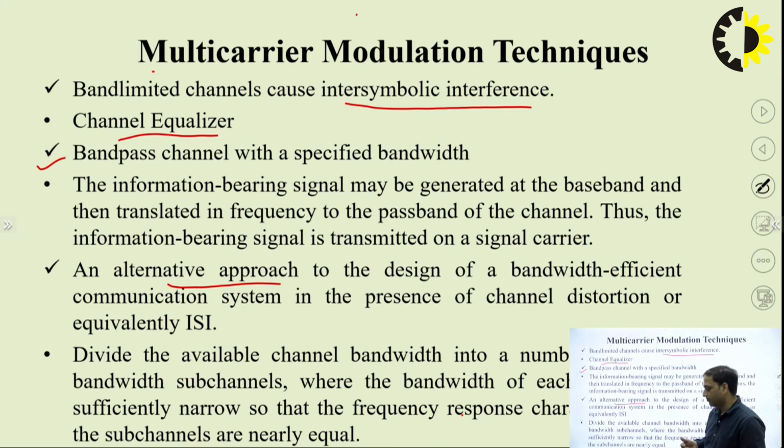So what is the procedure for that? The third approach is, we simply divide the one band of frequency into different chunks of frequencies, or subcarriers. Second, we take the complete long stream of bits and divide it into small chunks of bits.